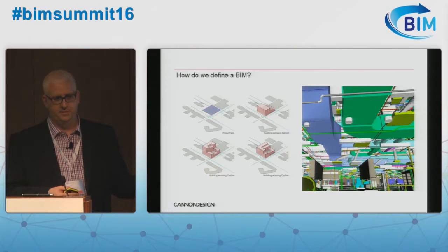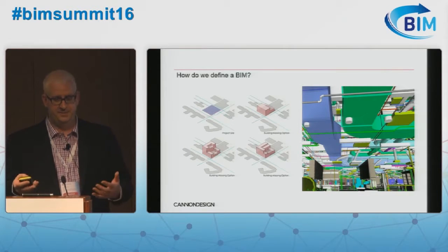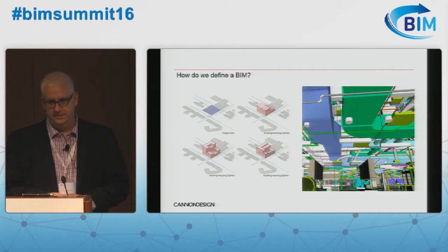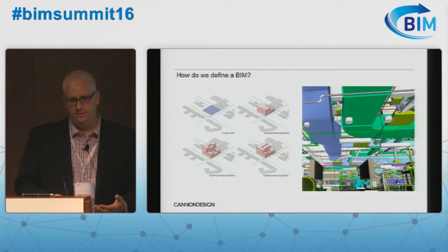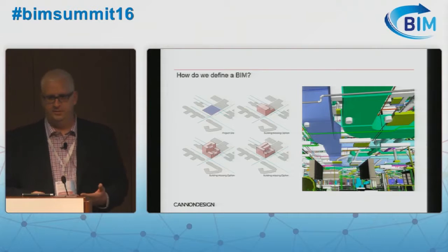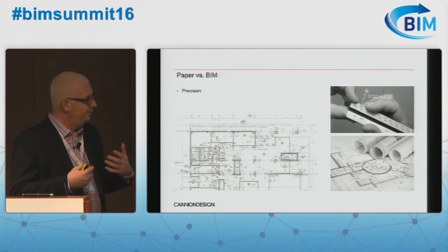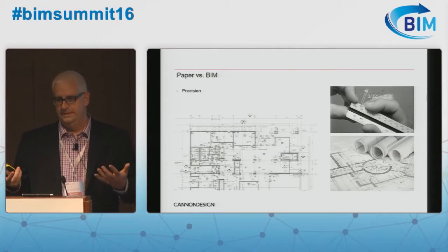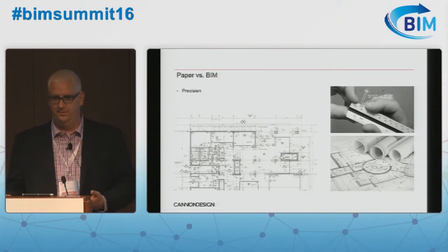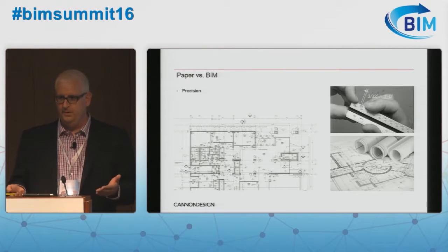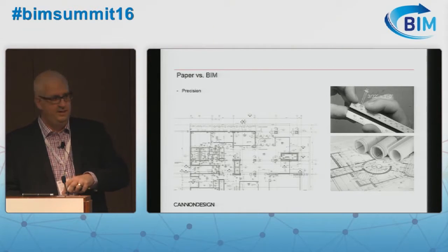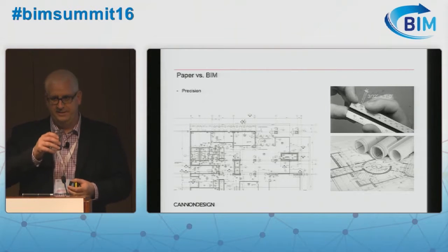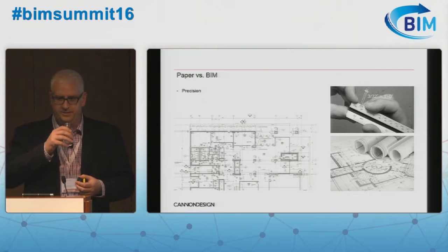One's going to be based on a cost per square foot. The other is going to be based on actual specific components and elements that are to be installed and fabricated about a building. So when we start to look at these and conveying information about what's there, this isn't a problem that we had with CAD. This isn't a problem that we had with those 2D paper-based outputs, because we were reliant on putting everything we knew down on paper. If it wasn't down on paper, it wasn't clarified, it had to be asked. There were no real assumptions. If we needed a dimension, we had a precision or a tolerance accuracy. We put a dimension on the drawing. It was very clear what it was. If you had an 1/8-inch drawing, somebody wasn't going to be able to scale off of it and have any reliability to that information that was in place.